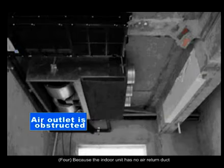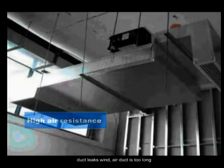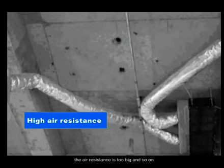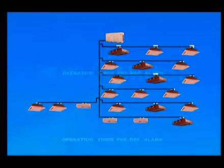4. Because the indoor unit has no air return duct, the duct leaks wind, the air duct is too long, the air resistance is too big and so on, these can cause the indoor load to become bigger and performance to become bad.